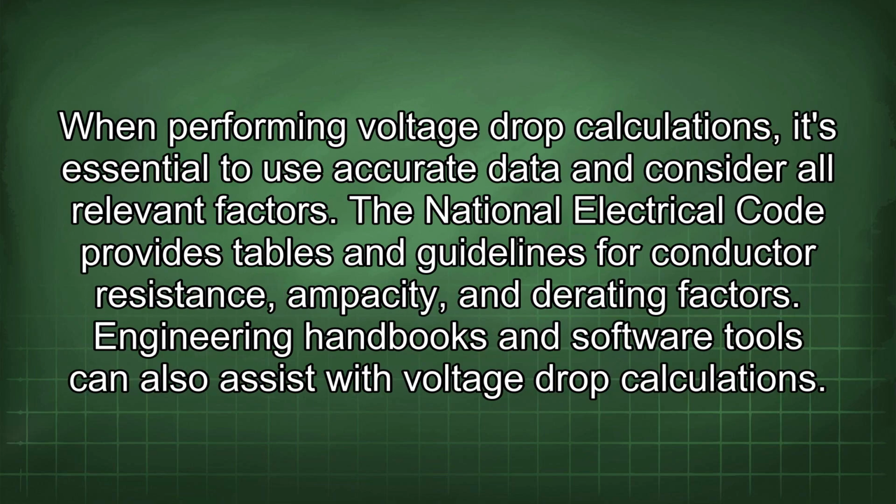When performing voltage drop calculations, it's essential to use accurate data and consider all relevant factors. The National Electrical Code provides tables and guidelines for conductor resistance, ampacity, and derating factors. Engineering handbooks and software tools can also assist with voltage drop calculations.